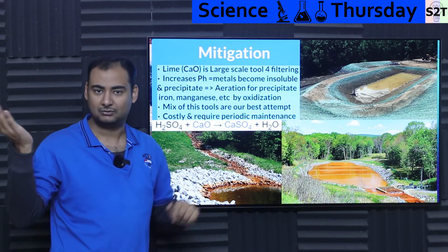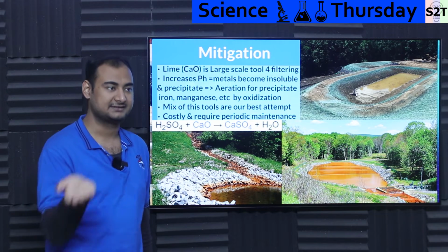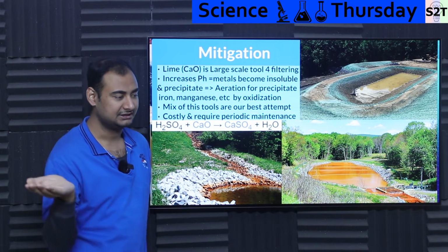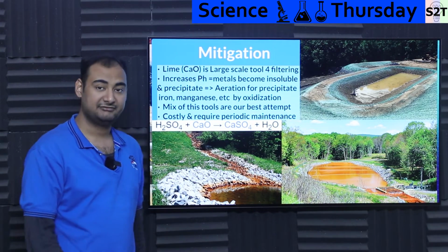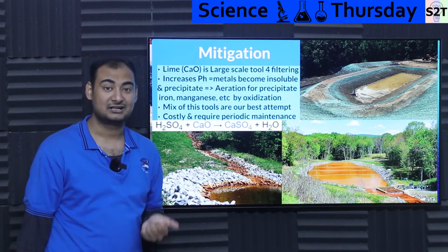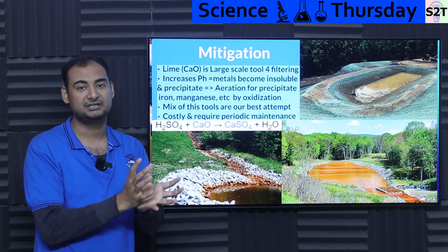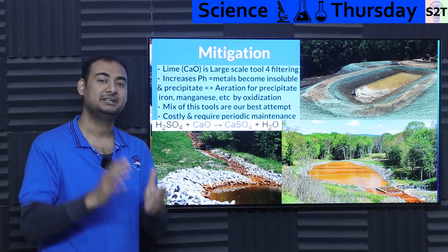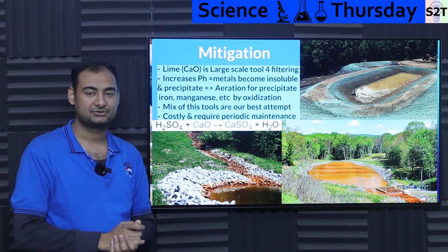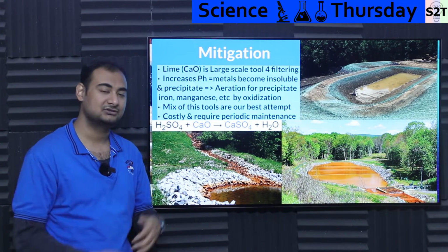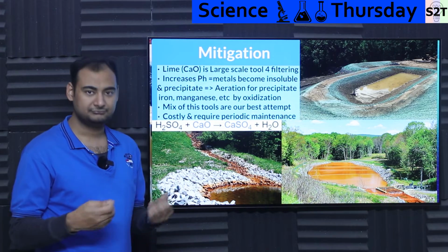Basically, pond A, water comes in, pH level goes down, as in goes up. Basically, it goes from acid to base, or acid to neutral, and you just move it to the second pond. Now you dump a bonkers amount of oxygen, and the benefit of that is your limestone does not run out as quickly, meaning it does not become isolated, covered in gunk. Yeah, that's the best way of putting it. You basically delay how long it takes to gunk up the limestone, and you can get more oomph out of every truck of limestone that you have shipped. So that's a clever usage of it.